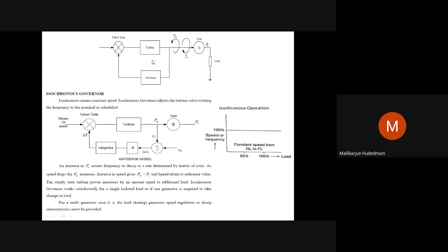Then in the lower block, the governor, what is inside that isochronous mode? That is the power, again a pickup of RPM from the output, then RPM set, which is omega naught, and omega actual, which is what it is running at, then a comparison of that as an error. That error with the gain, amplify it and integrate over a period mentioned.